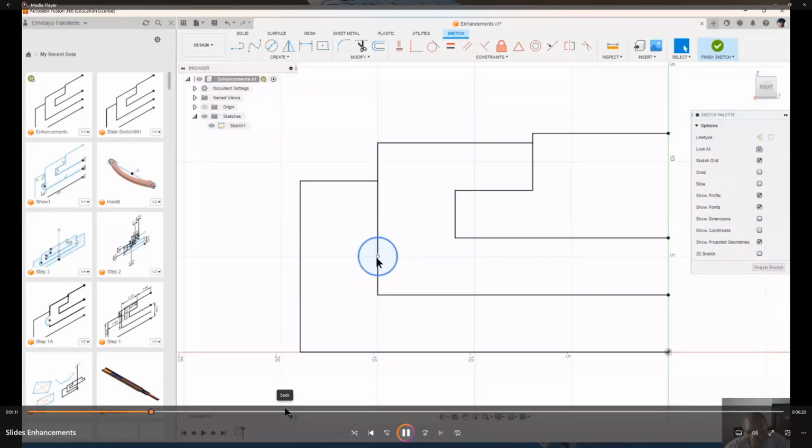we can specify the horizontal and vertical distances from a particularly known point. The horizontal distance is known since it is lying on this line. So what we really need to worry about is the vertical distance. We can take a dimension tool and measure from here to the origin, the vertical displacement. Let us make that 5. If we make that 5 units, then it is already turned black.